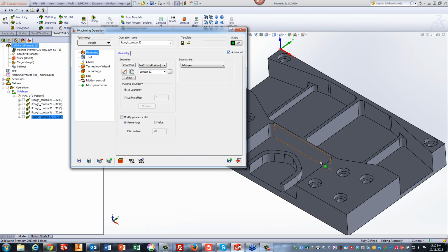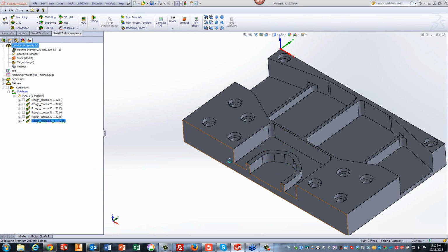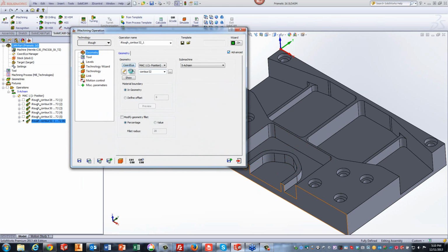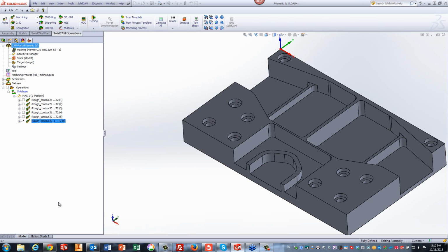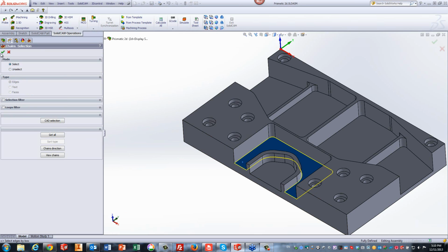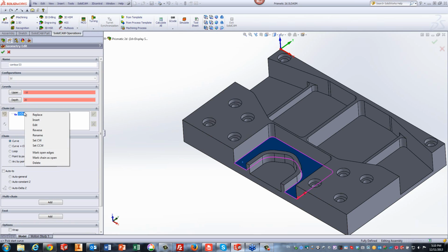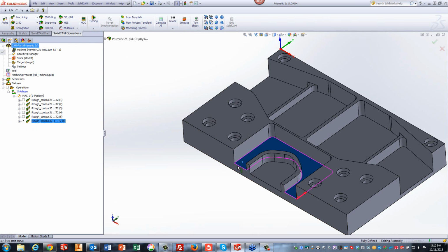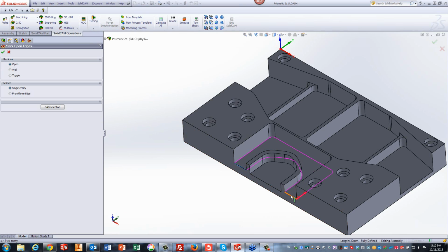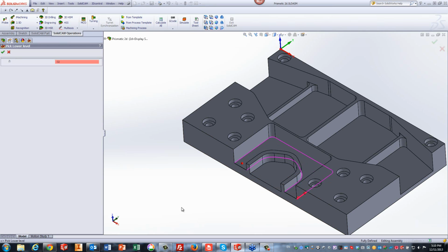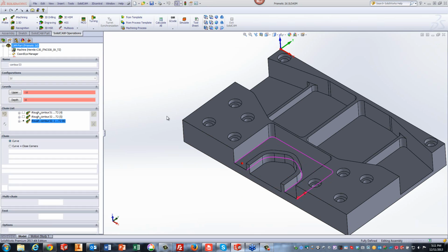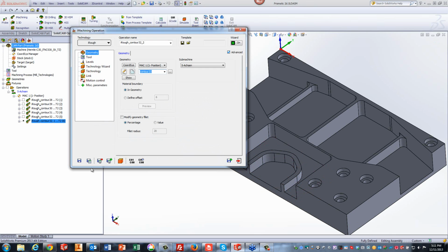And one more time, just for this surface over here, we'll do again, save and copy. Create a new geometry again. Again, I like using the option of multi-chain and just clicking on this surface over here. And then just mark my open edges by clicking on this edge over there and this edge over there, those two curves over there. My depth this time, however, is up until that surface over there. Now, I'll click on OK, save and calculate.